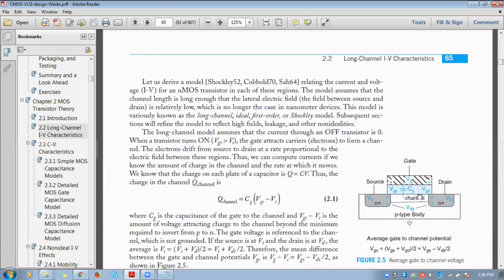Due to velocity saturation, as the number of electrons gets reduced inside the channel, due to the lateral electric field, the speed and mobility get affected. That's why, in velocity saturation, a constant velocity will be gained by your electrons. So we can't further improve the speed. As speed decreases, your current flow also decreases, as the number of electrons inside the channel is less.